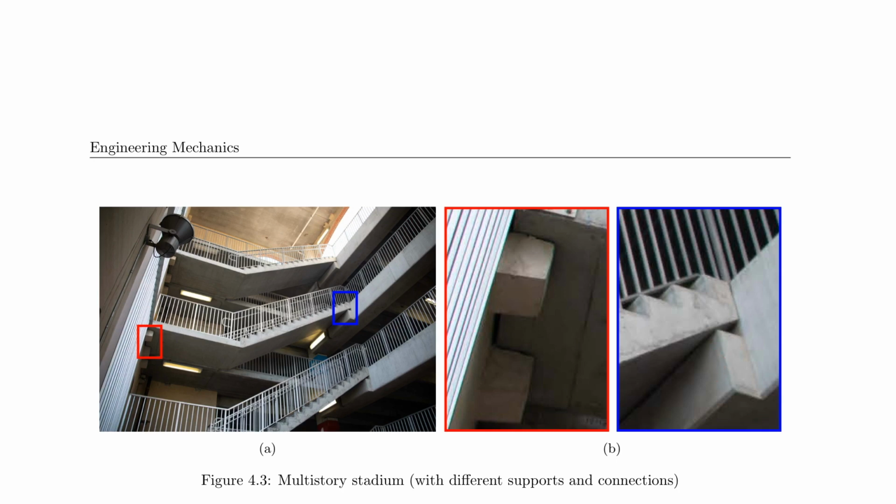You have one on each side. And what you cannot easily see in these images is that there's also a neoprene pad or something else underneath here, because engineers would never allow the concrete to just sit on top of the concrete. There has to be a friction barrier or something that allows friction, or motion, to be easily overcome. And we talk more about this when we talk about the degrees of freedom.